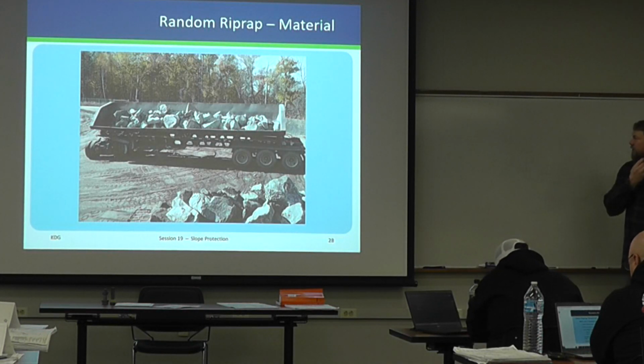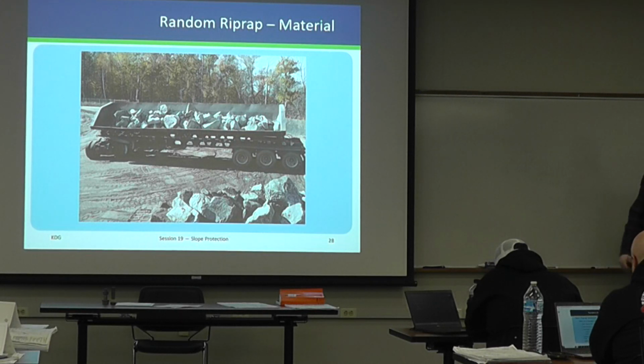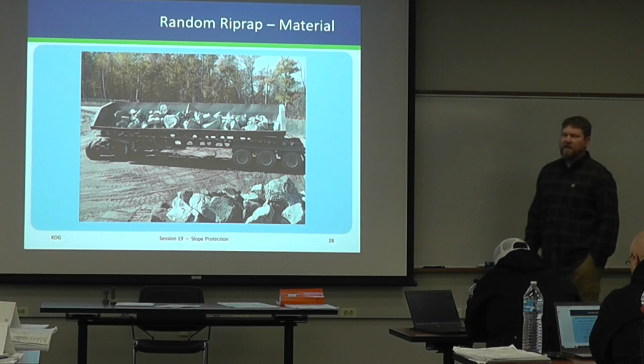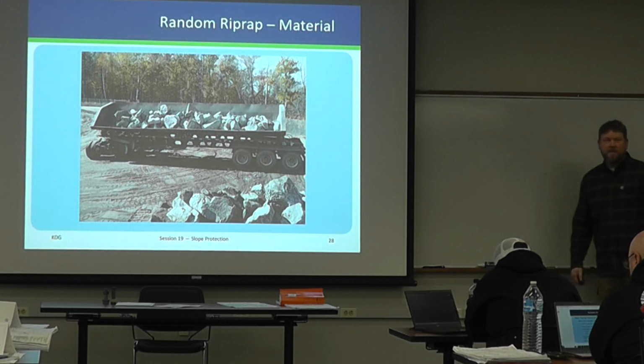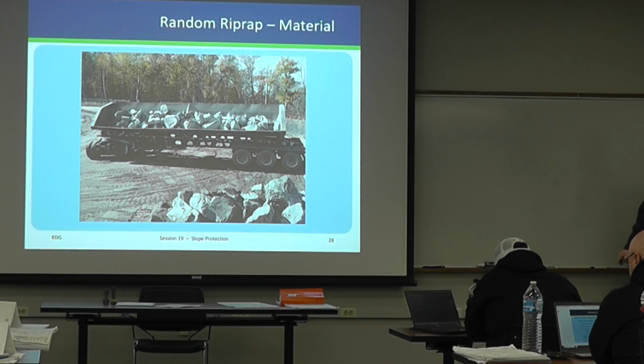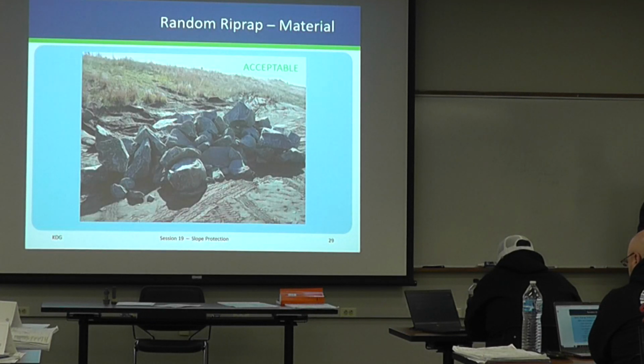So here's some riprap being delivered. Opinion here, does it meet the one fractured face requirement? I'm just kind of looking at the picture, do you think this is going to have material that's going to dissolve? Is it going to be soluble? No, I'd say this is a pretty good igneous rock, right? It's not sedimentary. Cleanliness, how does it look? Yep, looks pretty good coming out of the truck. Maybe in the stockpile they got a little there, but not too bad. Here's another picture of that material as it's sitting there, and it would be considered acceptable.